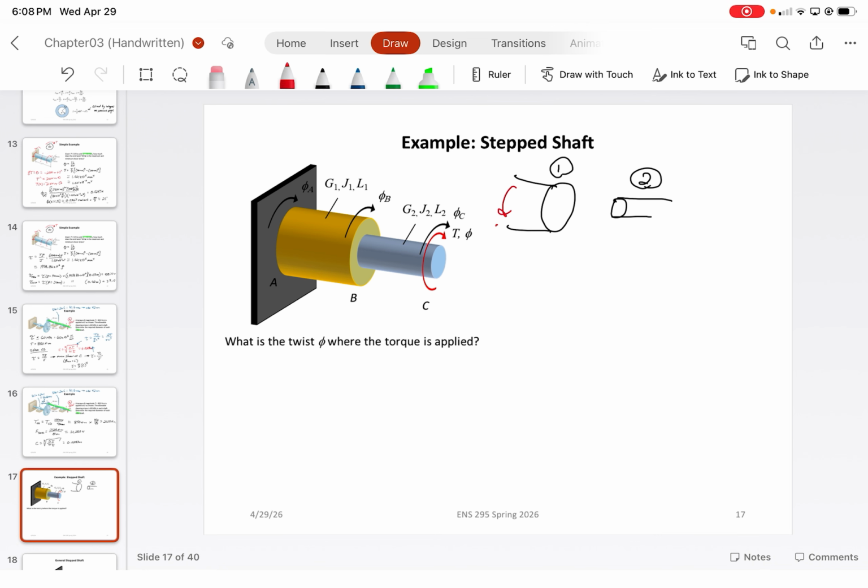We know that the torque that's felt here and the torque felt here also has to be felt there and there, right? So the torque is just transmitted. Granted, it's a nice easy case because there's only a single torque applied, but the same general rule would apply for several torques, which we'll actually get into in a little bit. All right, so that was the statics.